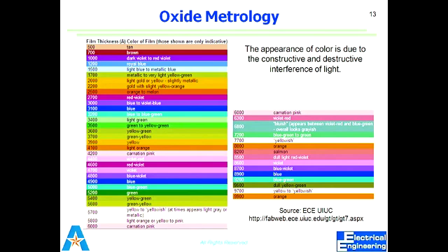After every thickness, you will see a change, but for the first few hundred angstroms, you won't see this. That's why it is starting from 500 angstroms. I would say after 600 or 700 angstroms, you will clearly see a color change in the wafer.